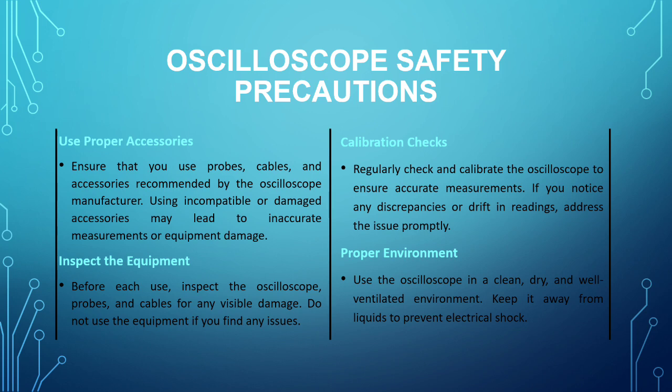Before we start using the oscilloscope, here are some safety precautions. First, use proper accessories. Ensure that you use probes, cables, and accessories recommended by the oscilloscope manufacturer. Using incompatible or damaged accessories may lead to inaccurate measurements or equipment damage.